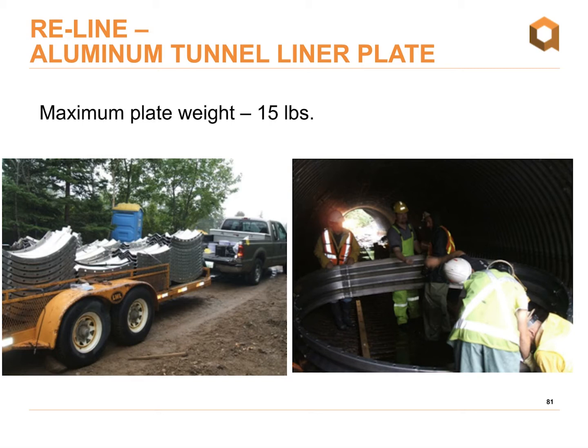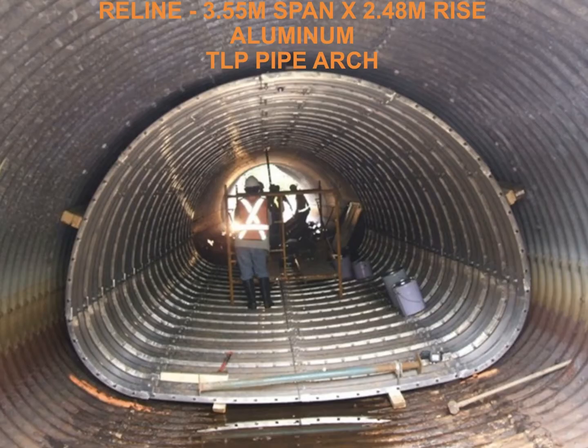Since the maximum individual weight of the aluminum tunnel liner plate was only 15 pounds in this case, the contractor was able to store the entire structure on a tag-along trailer and bring it home with him each evening. The light weight also enabled, of course, the workers to install this without the use of heavy machinery.